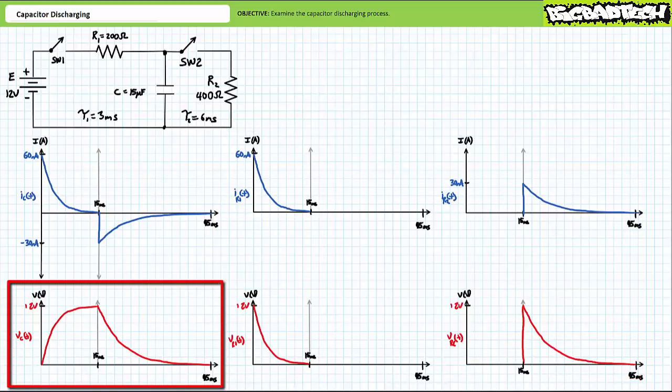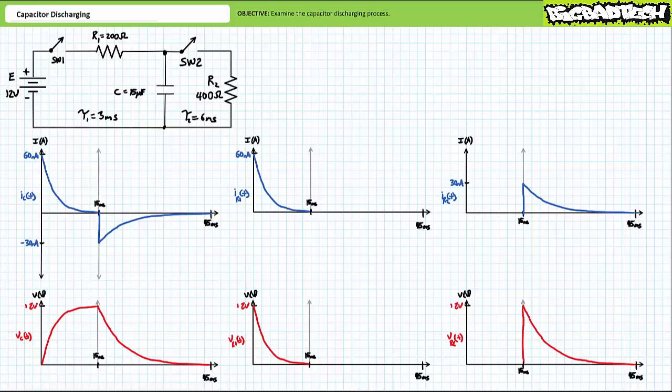Importantly, voltage across the capacitor, whether charging or discharging, never undergoes a disjointed instantaneous transition or sudden reversal. That's the point. Capacitors resist sudden changes in voltage and are often employed in circuits that necessitate relatively steady or slowly changing voltage conditions. Additionally, you note the asymmetry of the charge and discharge process.